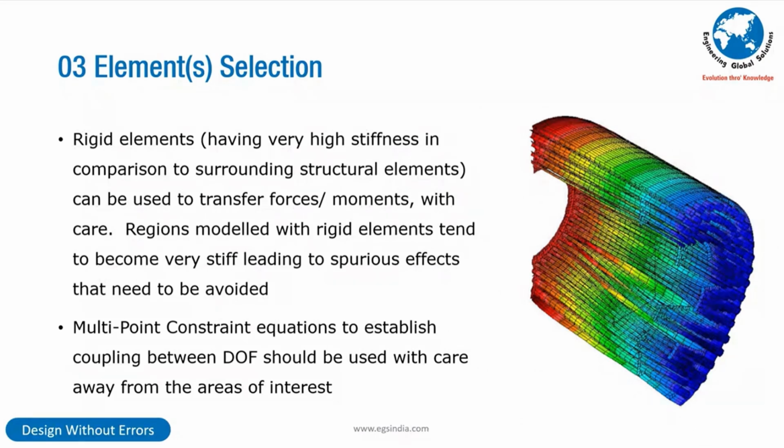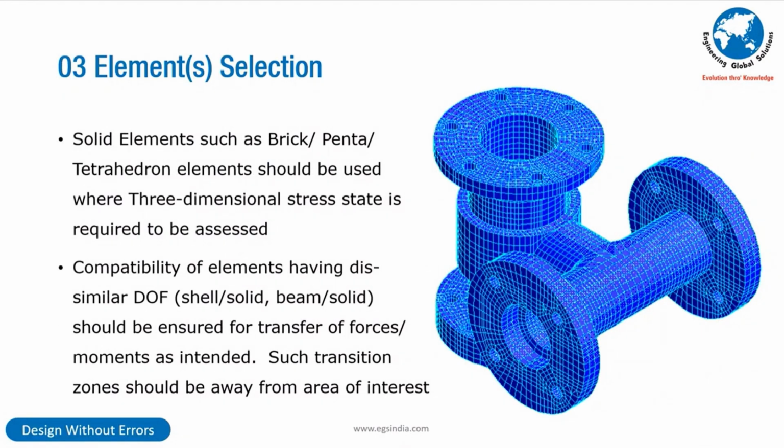I'm giving you different examples here. When you look at the previous example, you see how nicely the flanges are modeled. Why is it modeled like that? Because we were looking for the leakages through the flanges, with the pretension coming in as a result of the assembly torquing. So the modeling has to incorporate that so that the contact pressure areas can be very clearly brought about and the contiguous zones mapped so that the leakage is prevented. Because leak is a big problem, right? Especially if it's a corrosive fluid.